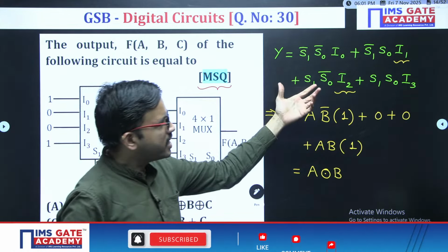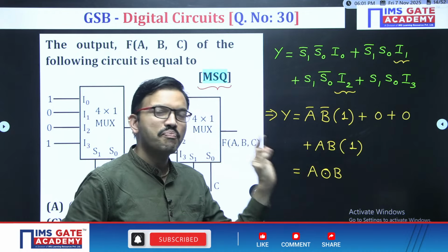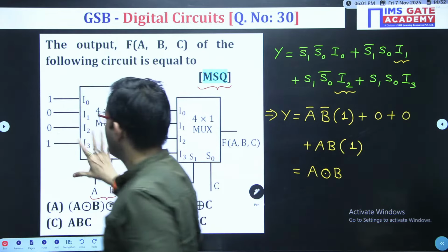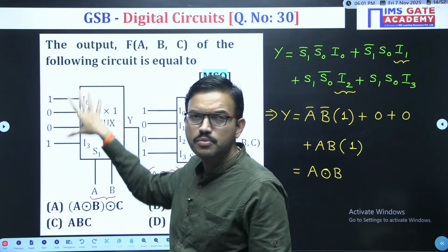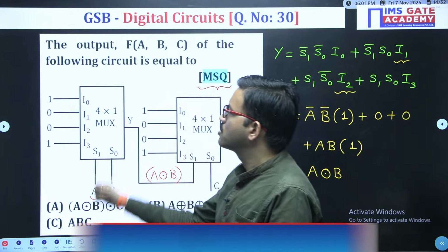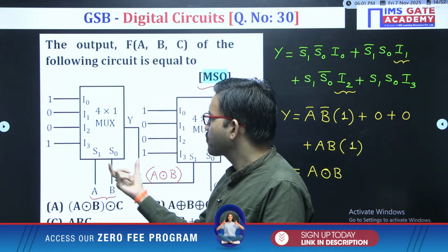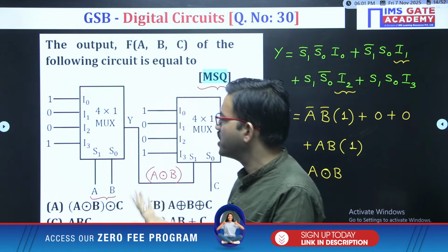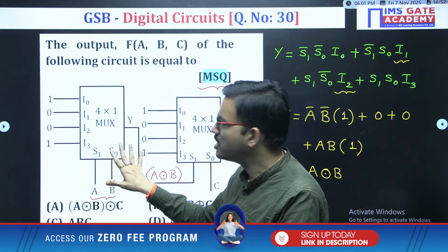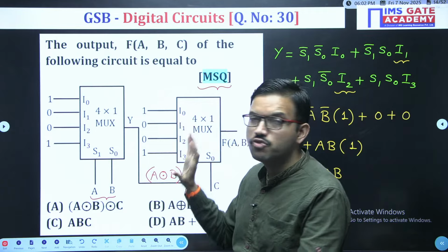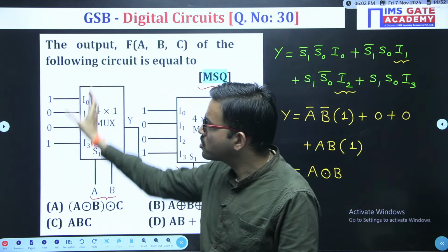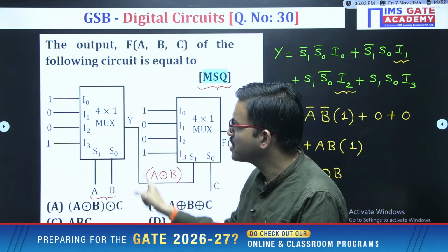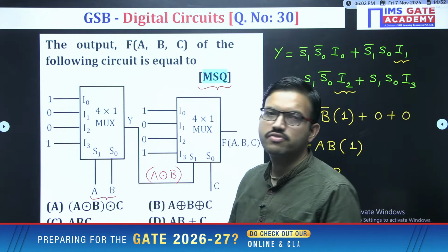With the help of the logical expression, you get the same expression. Once you observe that for any mux the inputs are a combination of ones and zeros, just observe how many selections you have with respect to the logic gate. Here 2 selections are there, that means 2 inputs. With respect to which 2-input logic gate you get this output column, that logical operation you have to perform among the selections, or among the respective variables. That's all.